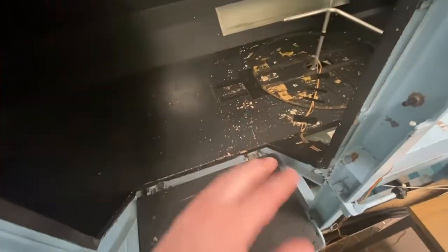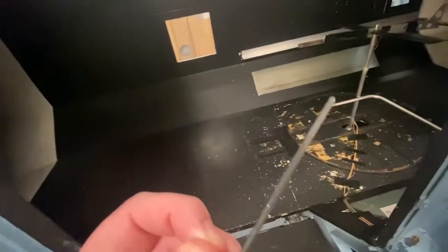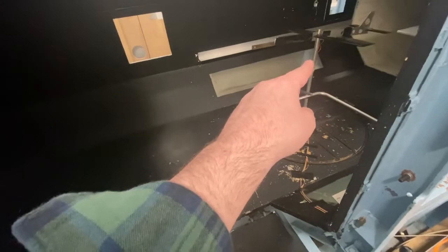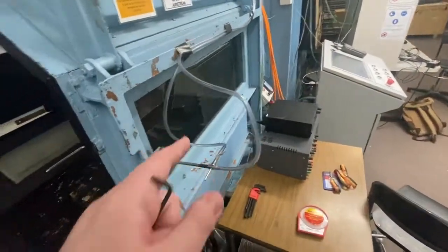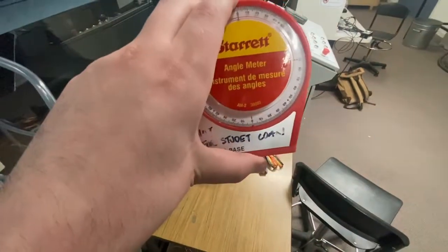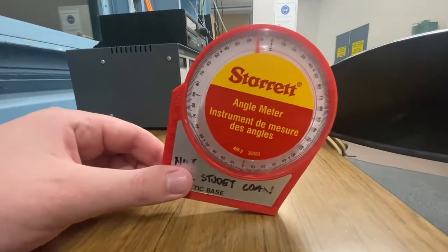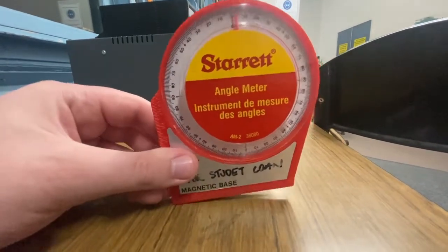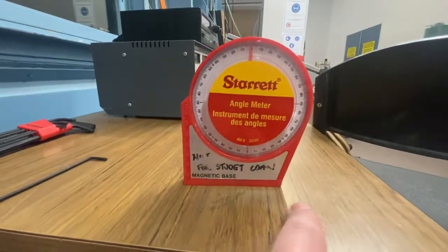So we want to repeat what we did earlier. Take a 3mm Allen key and undo the bolt at the top of the pivot to change the angle of attack. Once that's secure, get your partner to stand there and look through the window, where we will take the angle meter, sit it on a flat surface and ensure we have the right angle. Just a note on the angle meter, it is quite sensitive as you can see. So when using it, ensure it is on a flat surface and take measurements as accurately as possible.